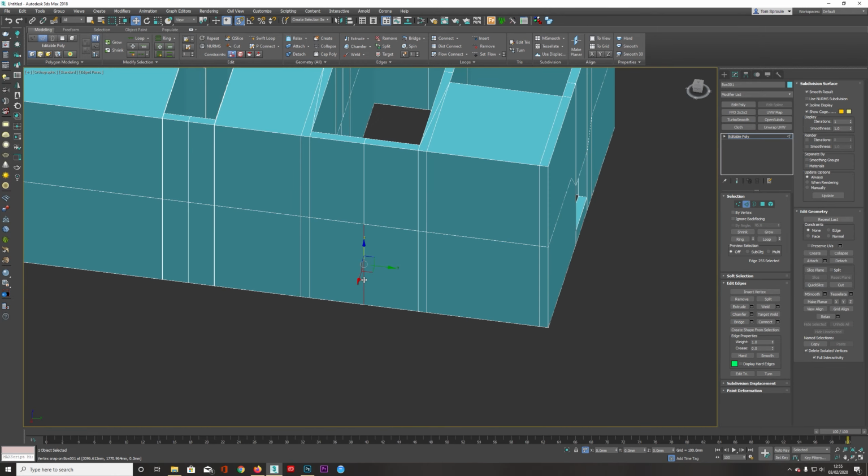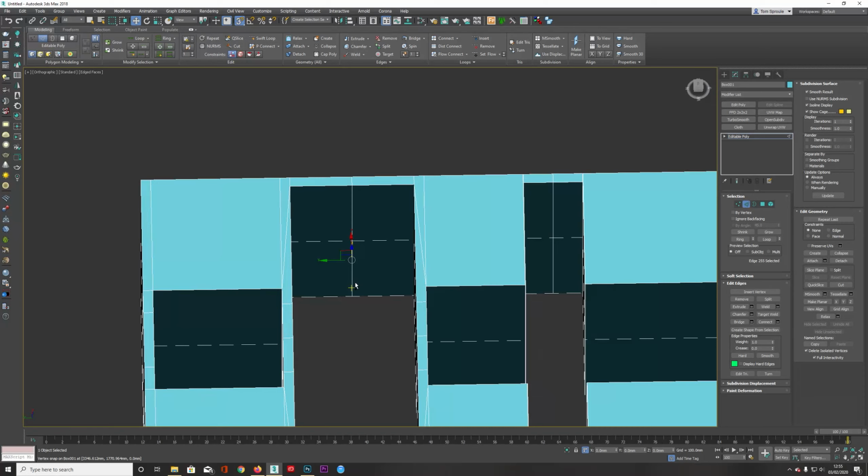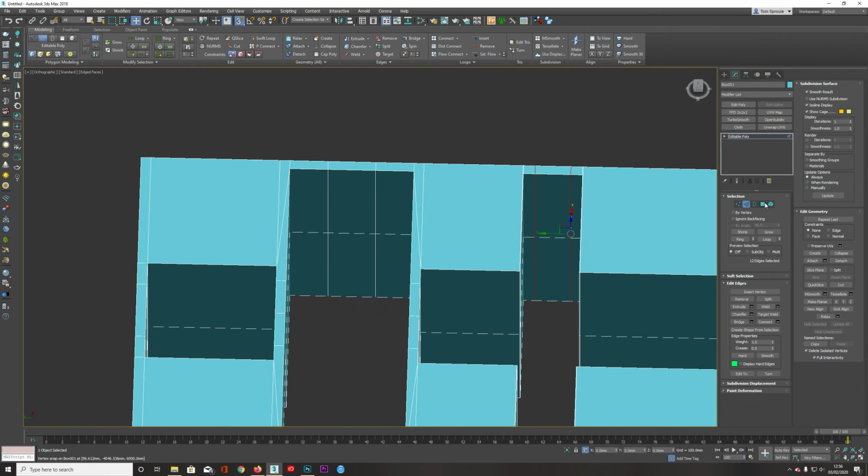So that's okay, we're just going to take this, left click, get that all the way around, click chamfer, and let's do 1 meter 20. Then left click here, and I'm going to chamfer this less, let's say 900 in total, so 450, as this is a smaller corridor. I know it's a small door, but for now that'll work.